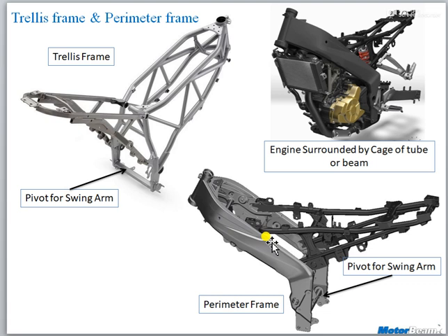Okay, if you look at the other end, that is damage of chassis or damage of frame, then it is easy to repair in this case, because if some longitudinal or lateral member gets rusted, then we can easily cut it down and weld another pipe over here to again regain its rigidity. But here if any portion or a rusted hole occurs on that box section, then definitely it is not that easy to repair. Okay, so this is the thing: repairability के मामले aspect में if you have a look, then definitely the trellis frame is more repairable than the perimeter. If one of the members gets bent, then it is easy to